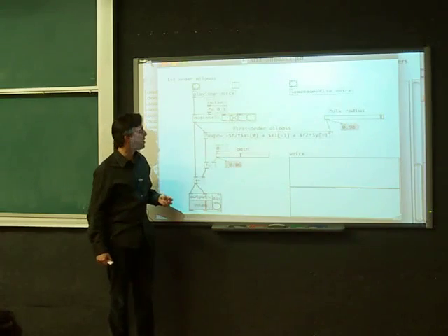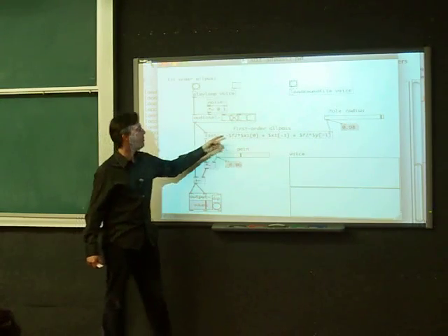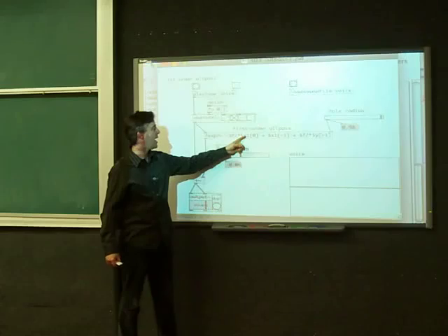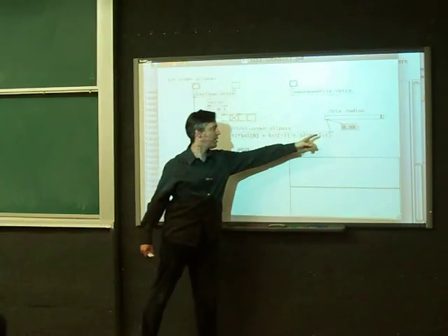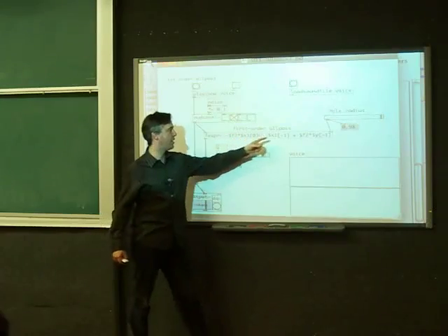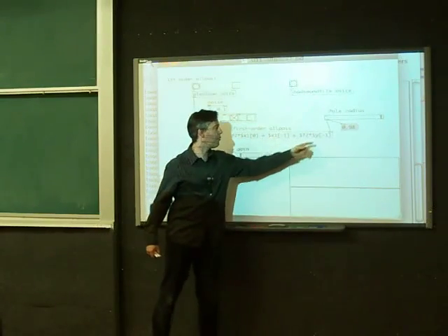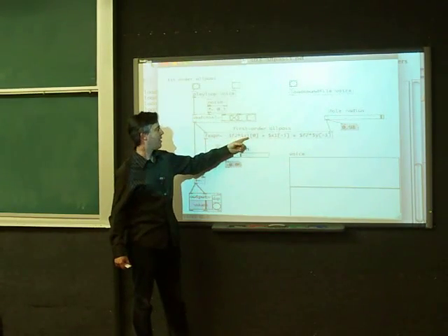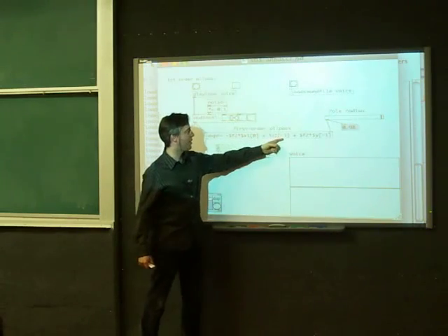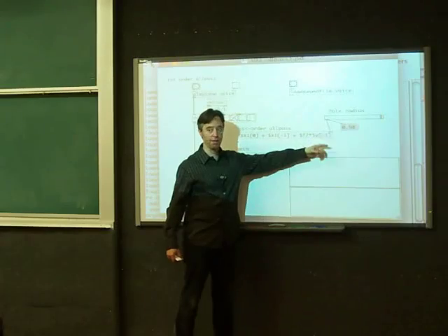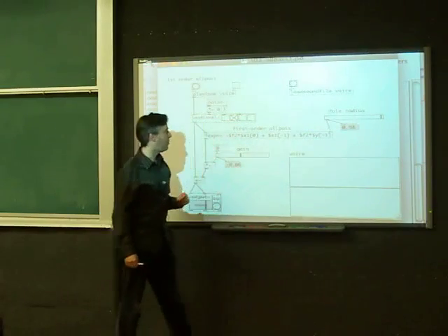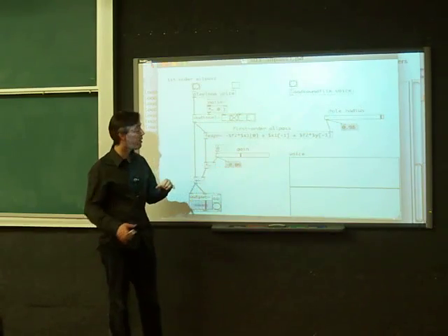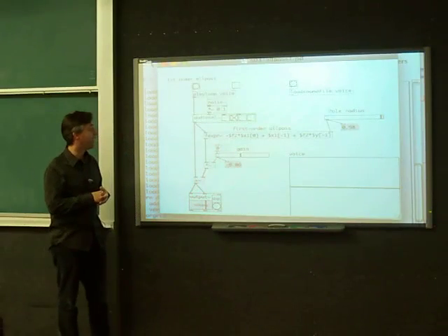to the signal. The actual inputs depend on what you put in the expression, but it's saying there's one input x, and there's another input which is just a constant f2 because it's the second input. Then there's the output y, and so the output is now minus the constant times the current input plus the previous input plus the constant times the previous output, which is how you implement a first-order all-pass. It's got one pole and one zero, and they're implemented in complementary places.